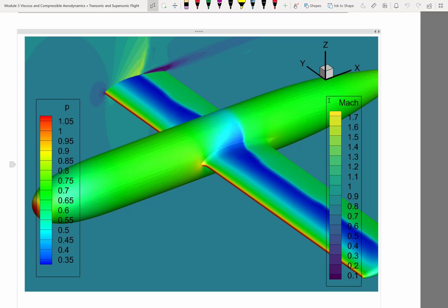There is no natural way for the flow to transition from a supersonic condition back to a subsonic condition, right? Because the supersonic region cannot last forever. The flow downstream has to become subsonic again. But in order for the flow to slowly go from supersonic back to subsonic, you need something that doesn't occur in this geometry. You need the stream tube to shrink again, right? In supersonic flows, if you want to decelerate, you need to shrink the stream tubes,